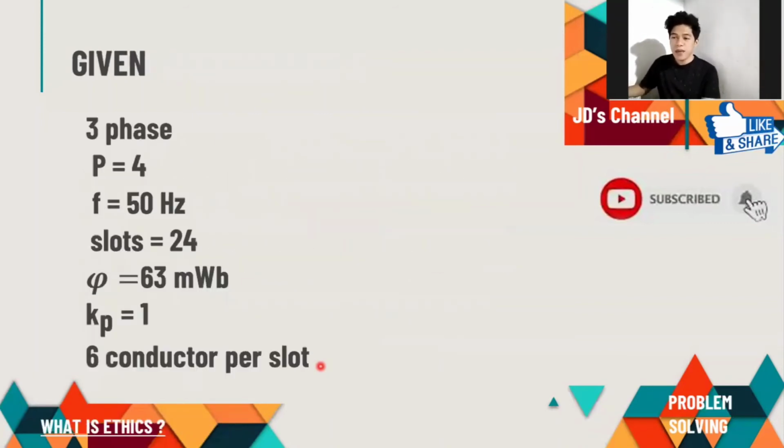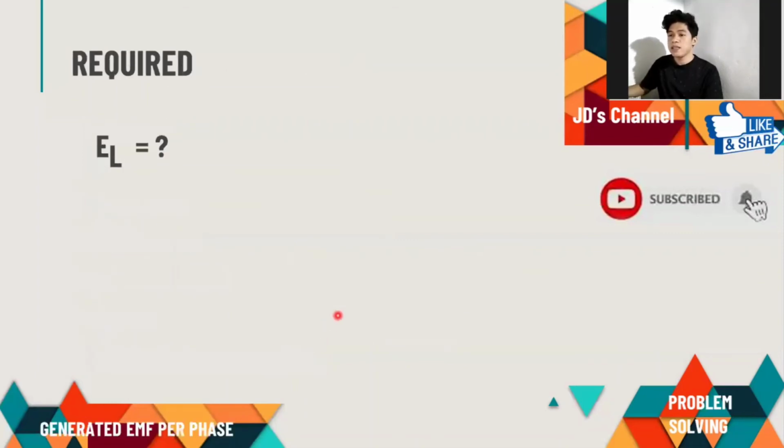So we have 3-phase, P which is 4, frequency of 50 hertz, and 24 slots. Our flux is 63 milliweber. We have KP equal to 1, and 6 conductors per slot. Okay, so we are going to find EL, since EL is the terminal voltage.